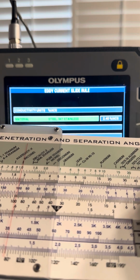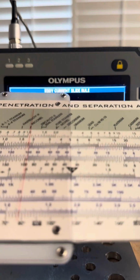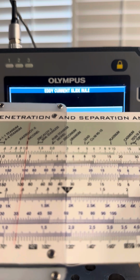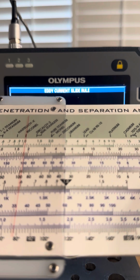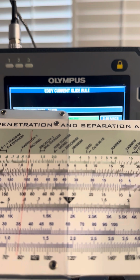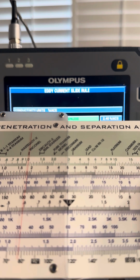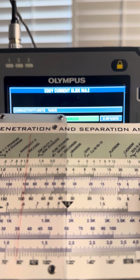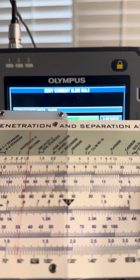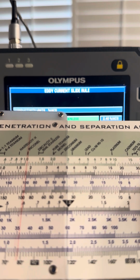And then one last thing you can do, what we were really doing there was calculating the right frequency to get a separation angle of 90. But when you're doing tubing and you're using phase for sizing, like OD flaws or far surface flaws, you'll use a phase versus depth curve. Normally you pick a frequency that will put your really shallow far surface flaws around 170 degrees or so.